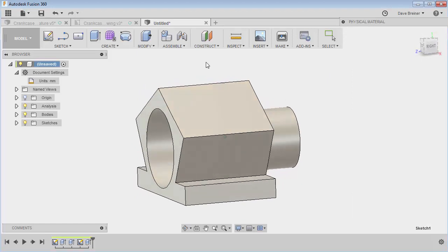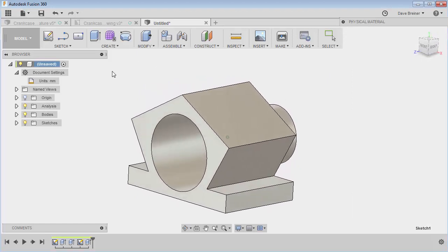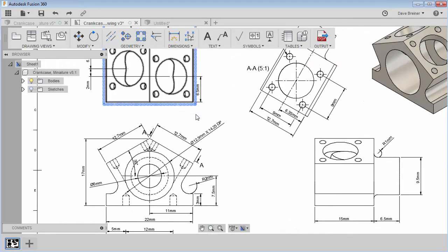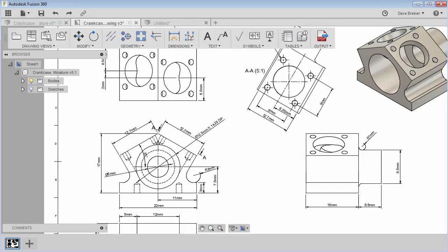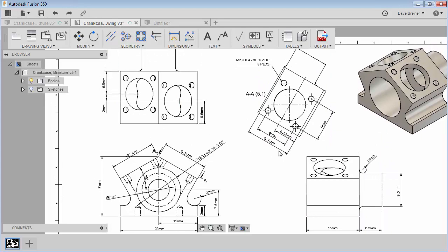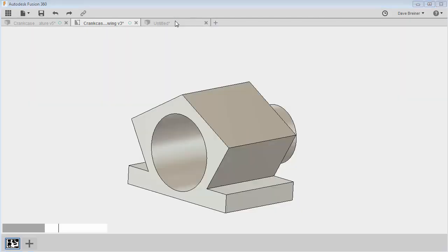And that looks nice. All right. So what I need to do now is come in and apply these holes. These holes are slightly offset, and it's going to be 6.5 in one direction and 6.35 up, and they're going to be the same on both sides. So let's see if we can try that.